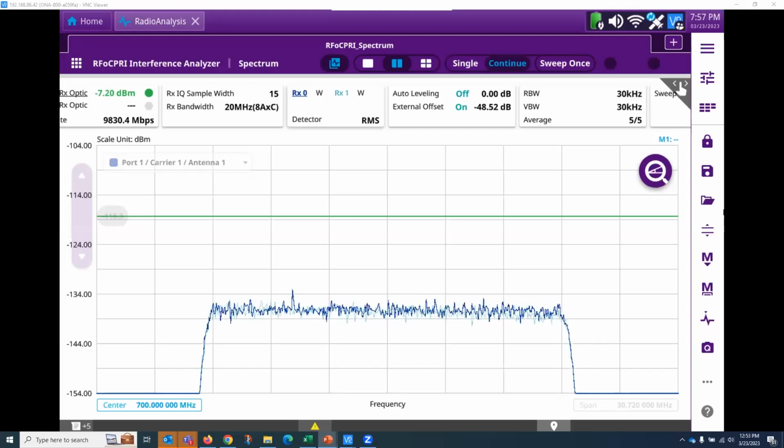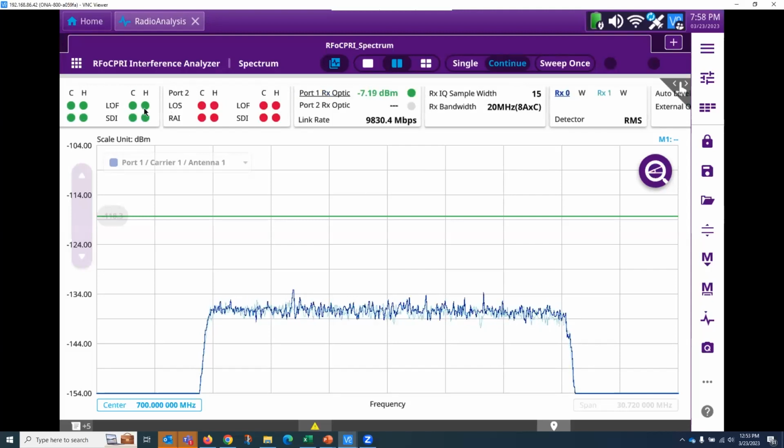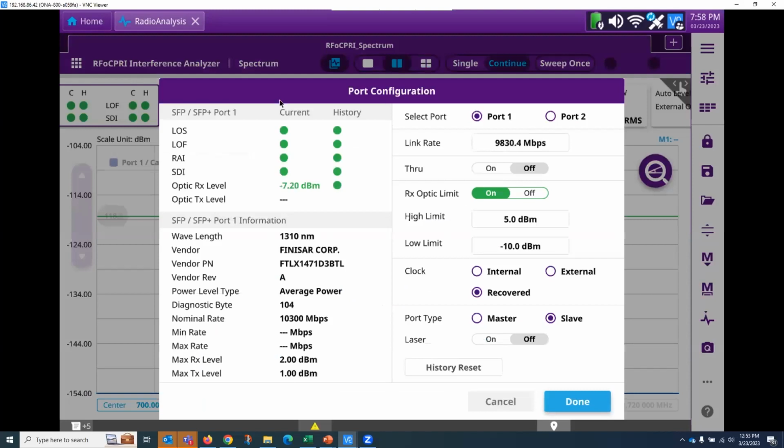Certainly. I'll walk you through a little bit of how you tap, just so we can see it. You can see it from a power level. This is the fiber tapping screen. We don't really show a lot. You disconnect the RRH, or RRU if you're in an Ericsson world, from your baseband unit or DUS, whatever you want to call it. In our tap, you plug that into port A, which we call A because it's for the antenna. Then you take a jumper fiber from port B, which goes to the baseband unit, hence port B.